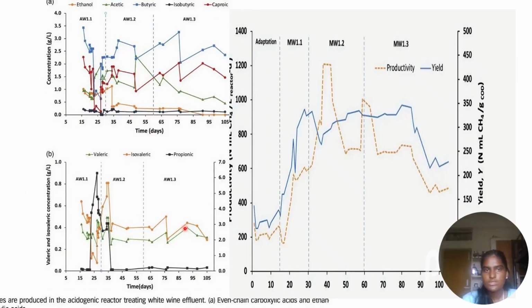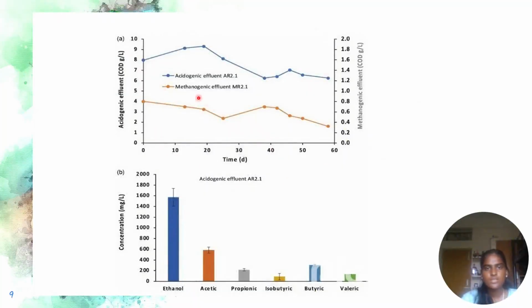It is a two-step process. First they carried out the acidogenesis in one fermenter, then they did the methanogenesis in another fermenter. Here in the red wine process, they did it in the same fermenter. First, it's stable in nature, like the acid production is stable in form. It's high and then it will be decreased. Then it will be utilized by the methanogenic bacteria, and it produces methane, and the concentration of the acetic and propionic acid as compared to the white wine is less.